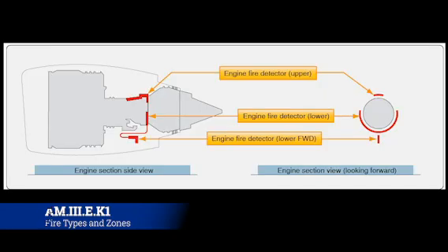All right, so now the power plant has several different designated fire zones. You have the engine section, the engine accessory section, except for reciprocating engines, any complete power plant compartment, so that's where it's located. Now, you also have the APU section, any fuel burning heater, like combustion heaters and things like that on a recip engine, but also on some of these heavy commercial engines, they have fuel heaters. The compressor and accessory sections for turbine engines, which is largely going to be fires due to bleed air leaks.